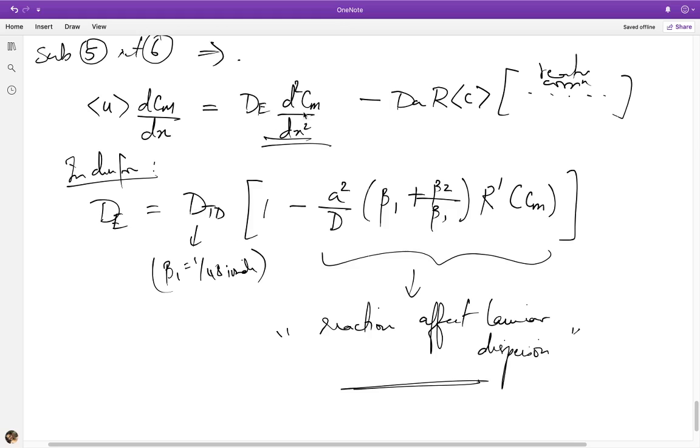So even though the use of a Taylor dispersion type axial dispersion model for a non-ideal plug flow reactor is valid, that is what this average equation seems to suggest, the dispersion coefficient you use there cannot be the same as that in the absence of a reaction. So you need to account for that correction. Or in other words, you should do an RTD study with the reaction occurring, not without the reaction. And also you have other corrections coming from the fact that the reaction rate applied at the average concentration is not the average of the true spatially varying reaction rates.